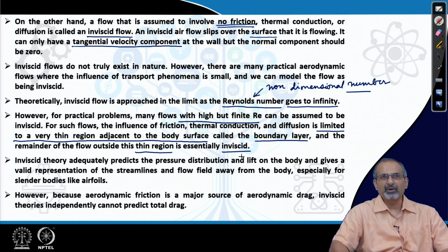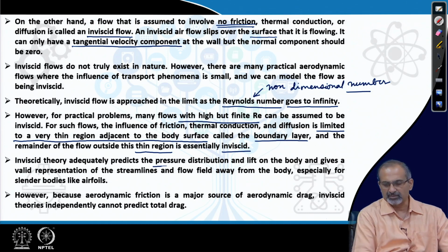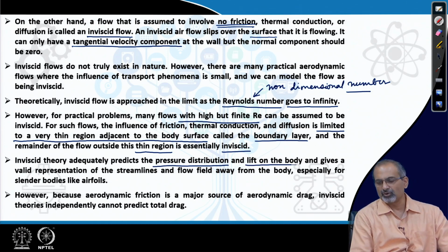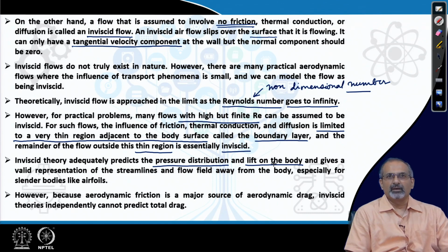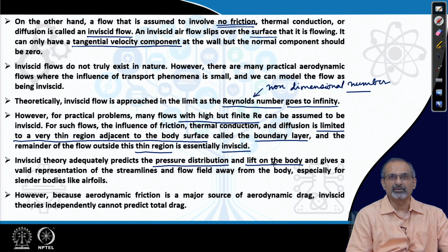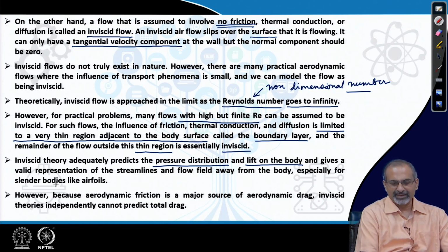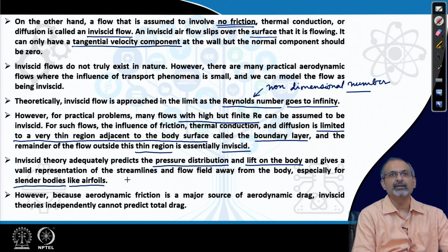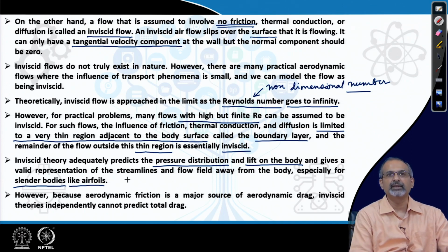Inviscid theory is very powerful in predicting pressure distribution, and therefore lift on the body, when the angle of attack is not substantially large. The results are very encouraging, and it can also predict the flow field patterns through the streamlines well. It is especially true for streamlined or slender bodies like airfoils, especially at low and moderate angles of attack.